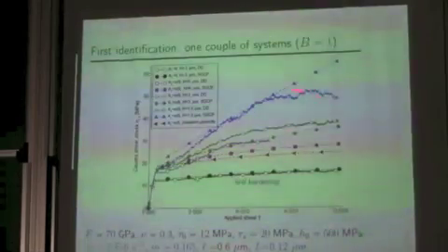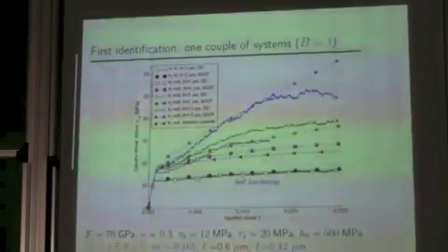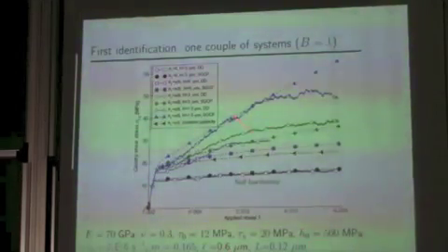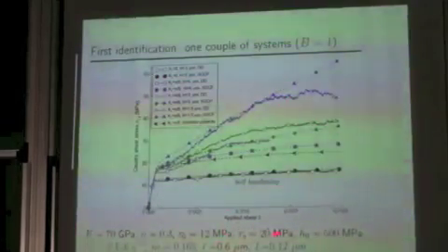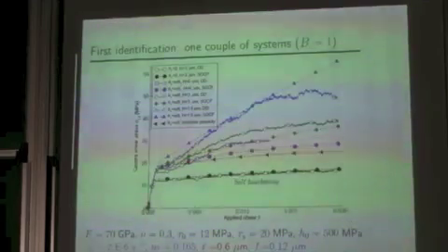You have to compare these two blue curves, these two green curves, and these two magenta curves. The brown curve is the one related to standard crystal plasticity, so of course it is independent of the size, and we could obtain this match by setting 0.6 micron for the energetic length scale,